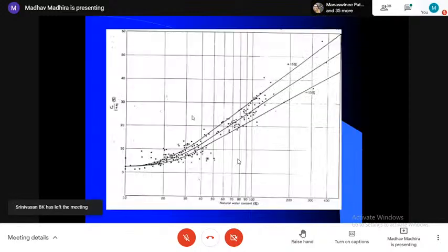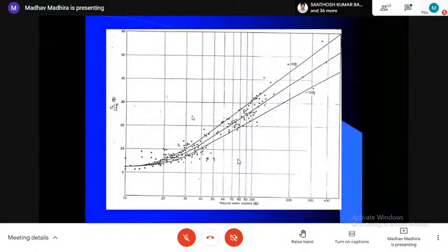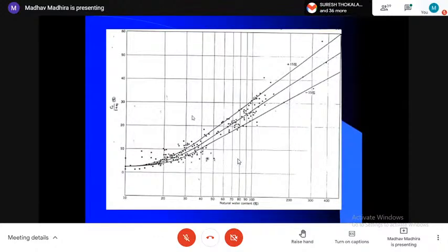And then I look at natural water content. If the natural water content is 70, I get worried because the compressibility is very high. If you look at this chart, around 80, the Cc by 1 plus e0, what we call the compression ratio, is of the order of 0.2, 0.25 to 0.3. And the settlement could be of the order of even 1 meter depending on the thickness of the stratum. The other thing I want you to remember is, if you're dealing with soft clay, try to get the natural water content. That gives you a very good handle to identify the seriousness of the problem.